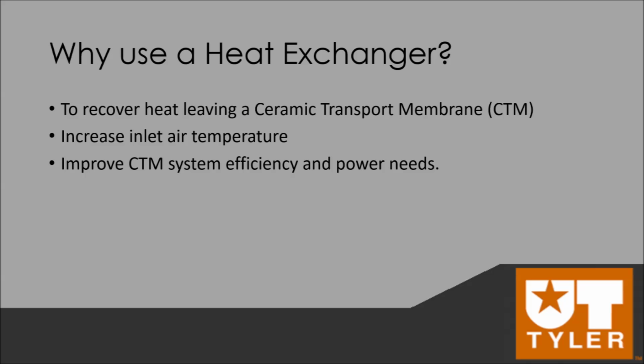For this oxygen supply system, the necessity of a heat exchanger is quite clear. This system intakes air at atmospheric conditions and heats it to a predetermined temperature necessary for a reaction within a ceramic transport membrane. Once the air reaches the appropriate temperature, it causes the air to diffuse into pure oxygen and oxygen-depleted air, which flow from the CTM to two separate outlets.